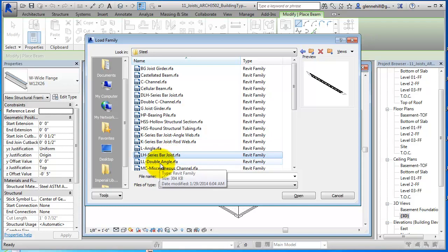All of these have different load capacity capabilities. The K series is probably the least load capacity of the series, but we're just going to use a K. It's one of the more commonly used, not always the most common. And once again, you need to talk with your engineers for them to tell you, well, this will probably take a K or an LH or whatever. So we're going to go with a bar joist with, instead of angle, a rod webbing, okay, instead of angled iron.